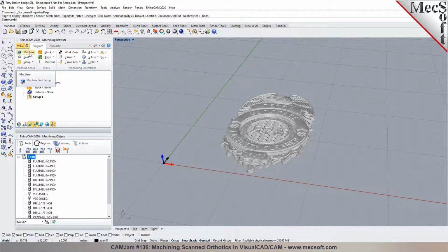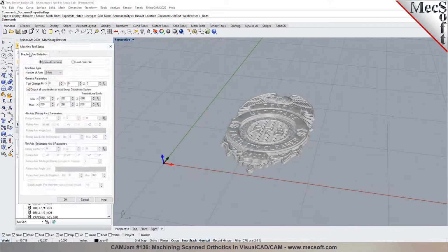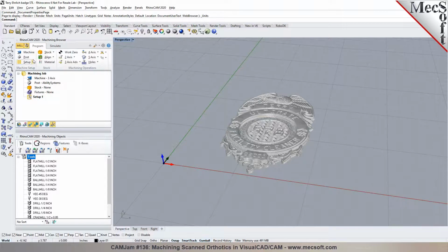So the typical workflow in here: the first step is you define your machining process. For 2- and 3-axis machining, you leave this as 3-axis. If you want to do multi-axis, 4- and 5-axis, these are available starting with expert and pro configurations to do 4-axis, index 5-axis. We also go all the way up to simultaneous 5-axis. But today we'll be primarily focusing on the 2- and 3-axis machining here. So you define the machine.